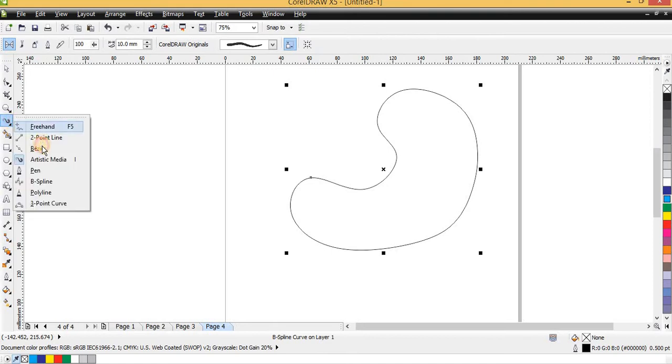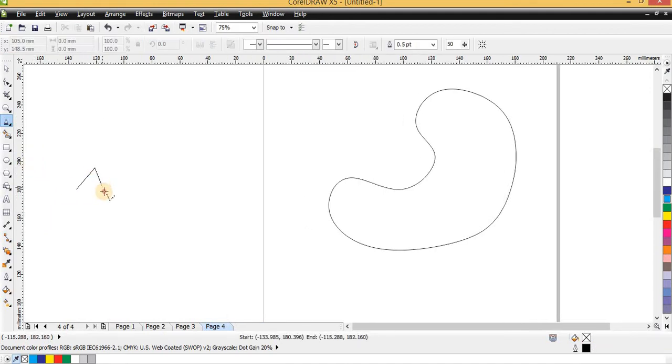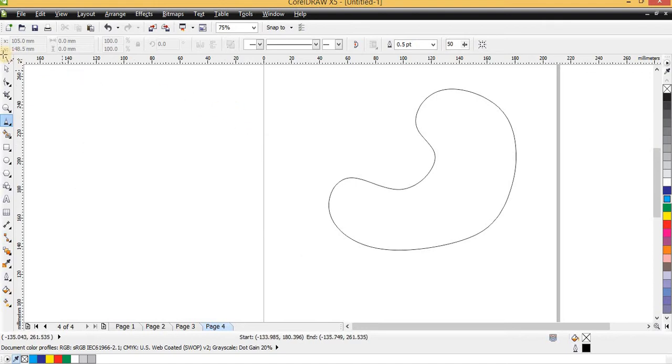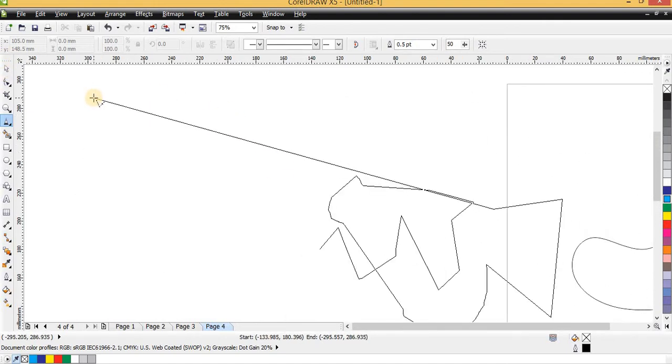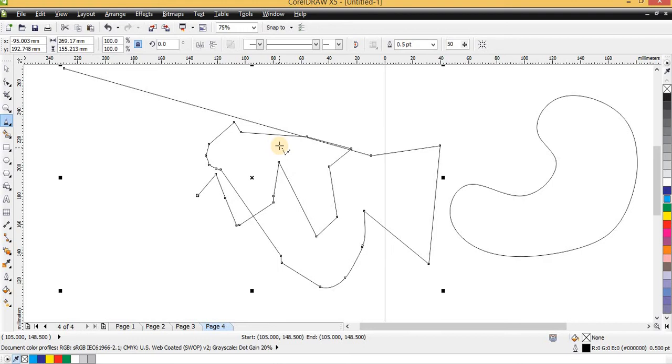All right, so the next thing here: we've done the spine tool, the polyline. The polyline tool helps you to draw lines, many segments of it, and it continues. You can draw a straight line or a curved line by just dragging, or you jump from point to point. It will never end until you pick the pick tool, which is like pressing spacebar. Polyline does not end. You have to end it by yourself, except you bring it back to the starting point.